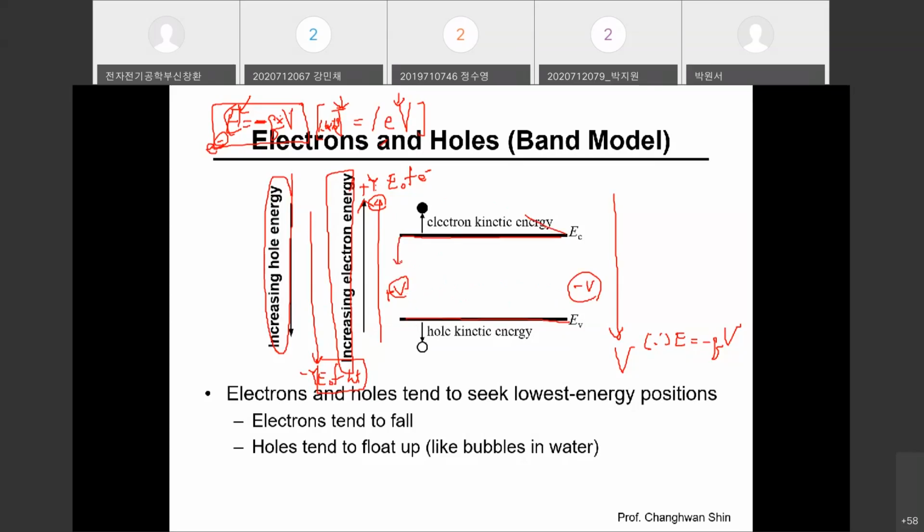Well, suppose that you apply 0.5 volt. Since the band gap energy is about 1.12 electron volts, 0.5 is about half of it. So this point would be positioned at the mid. Suppose that this position is simply ground, no voltage, 0 volt. You can draw it like that. Okay. So now, any band bending in the energy band diagram is closely associated with electrical energy, or the voltage that you apply.